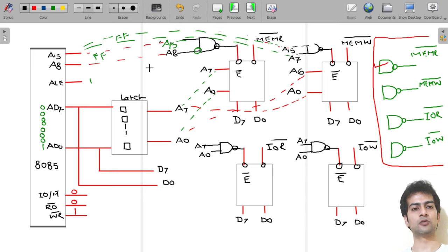So again, though the microprocessor is connected with both memories through hardwire, at a time only one memory would have been selected, based upon the memory address with which the microprocessor wants to communicate. Now coming to the third one, the control signals.